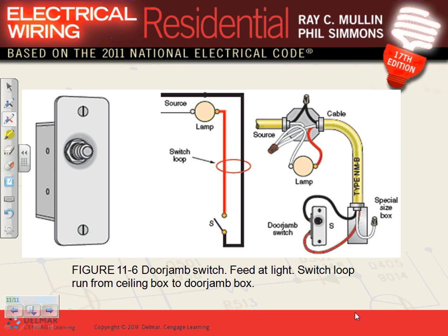You assemble this one in a box inside the frame, and that jamb switch is normally closed. How are we going to say that? Normally closed, held open. Normally closed, held open contact. So it's normally closed, but there's a pressure on it, held open.